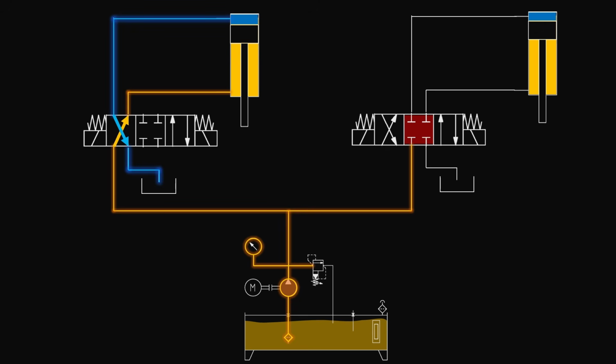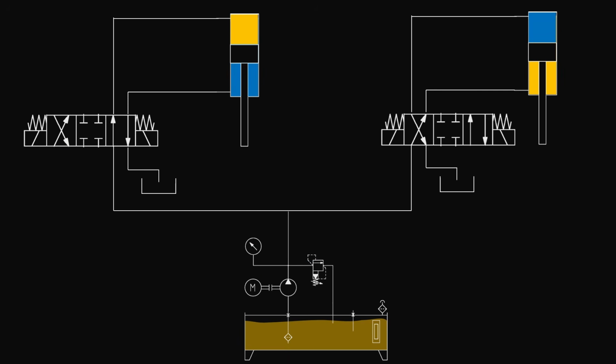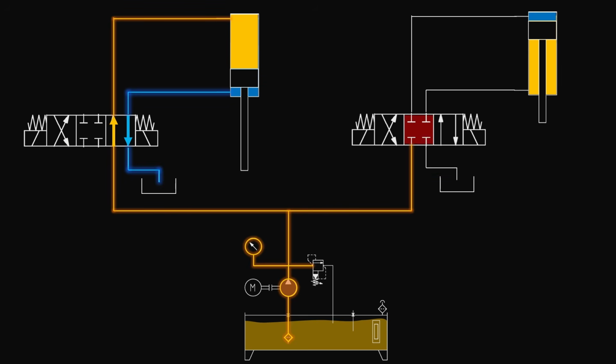And that's the main advantage of closed center directional control valve over tandem center directional control valve. So as a general guideline, a 4x3 tandem center valve is best when the system has a single actuator and we want to reduce the energy consumption while holding its position. But if the machine has multiple actuators which need to operate at different timing, then 4x3 closed center valve is